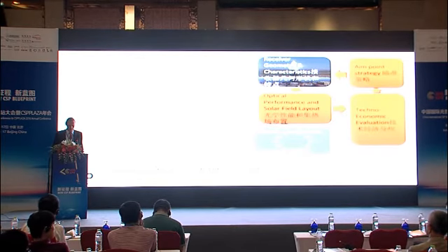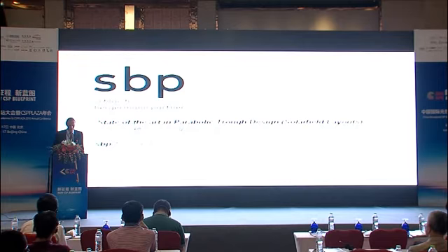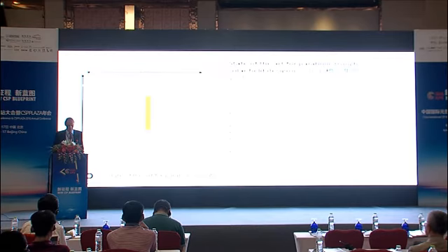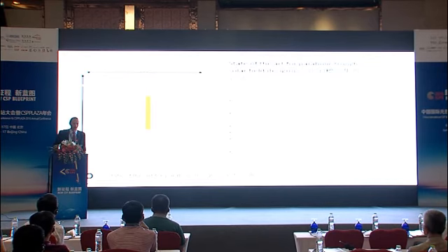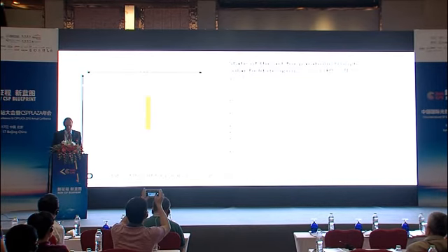So that's a power tower, but even on the parabolic trough, where layout seems to be simpler, you can get huge improvements by doing a techno-economic study. Getting to the first example, that's the parabolic trough system. You see the pictures quite often: the standard Spanish power plant, a 50 megawatt plant with 7.5 hours of storage. It has something like 500,000 square meters of mirrors and a plot size of 1.3 kilometers times 1.5 kilometers. So it's actually quite a large system.